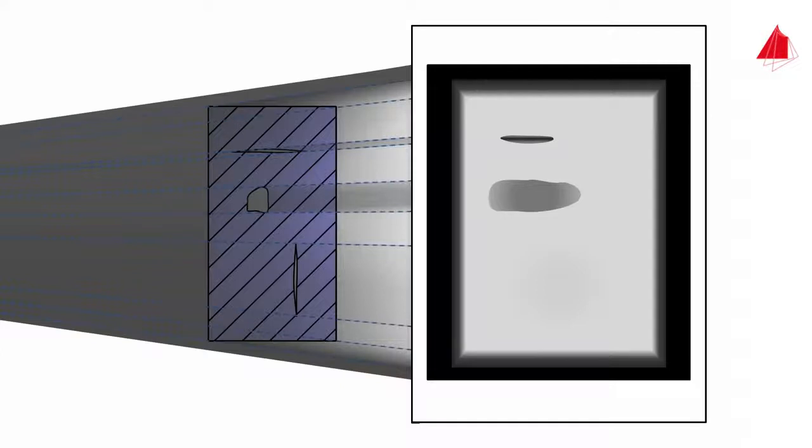But now there is another problem. The position of the defect in depth, that is, in beam propagation direction, cannot be determined with a single X-ray image alone. It hardly makes a difference in the image whether a defect in the sample is positioned further to the left or to the right.